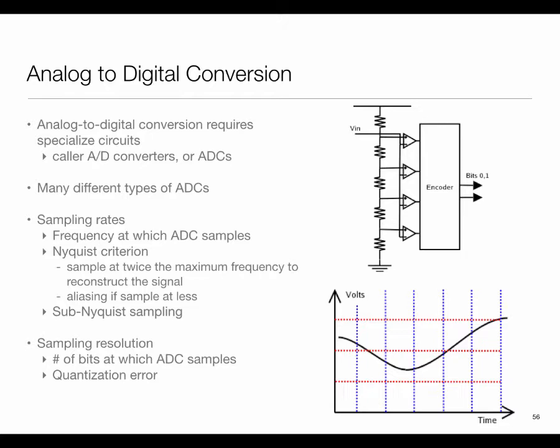The main thing is how often you have to sample. Okay, so classically in electrical engineering, we grow up with, and for those of you from CS it might be new, the so-called Nyquist criterion, which says if I have a signal and I want to reconstruct it, then I should sample it at twice the highest frequency present in that signal. So there are a couple of things. Firstly, the goal here is reconstructing the signal.